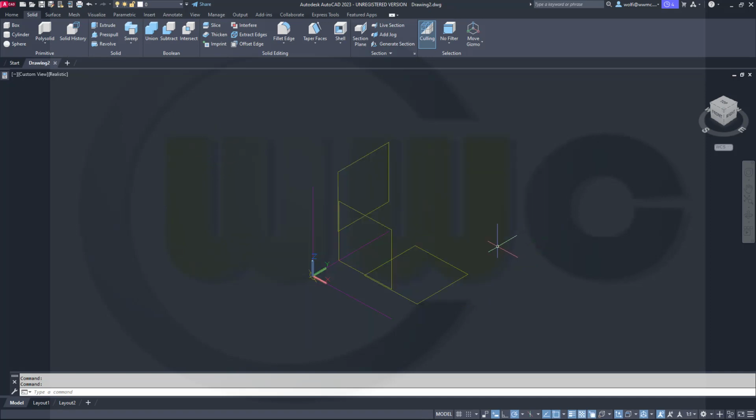Okay, I've already made a new drawing from my YouTube 3D template, and one quick piece of advice at the beginning: make sure your DELOBJ variable is set to 0. The default is 3, but set it to 0. Otherwise, if you have a polyline or a line and you make an extrude, that polyline or line or curve will be deleted, and we don't want that.